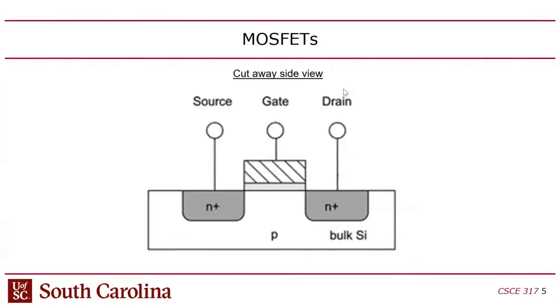Okay. So basically the way this thing works is that if this is an nMOS, which it is, we can tell because N is the source and drain. You have P-type as the bulk, or the substrate, or the body of the transistor. There's a lot of terms for that. And those have P-type, so it has the positive charge carriers, the holes, right? And then you ground it. It's important to ground that body.